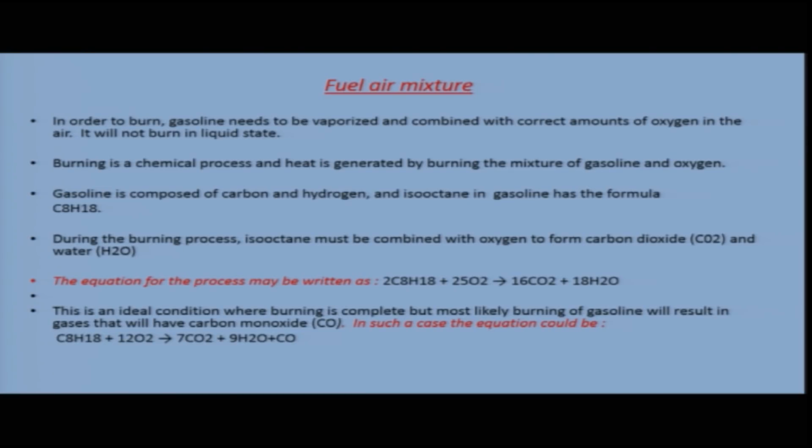So, let us see what is fuel air mixture. In order to burn, gasoline needs to be vaporized and combined with correct amounts of oxygen in air. It will not burn in liquid state. So, gasoline is not going to burn in liquid state, it has to be vaporized and it should combine with oxygen in the air so that combustion can take place.